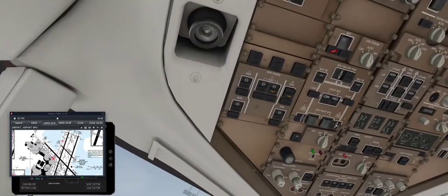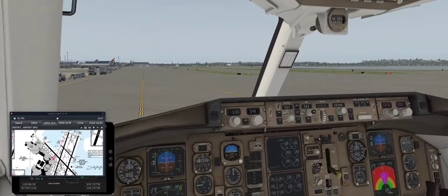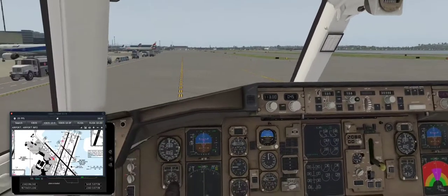And now we'll see this go off because the generators are getting turned by the engine, and that light will go off because now the engine is generating electricity via the generator, and we can also close the right generator hydraulics. We no longer need our APU. We can turn on our packs. And look at that. No warnings, everything's good.